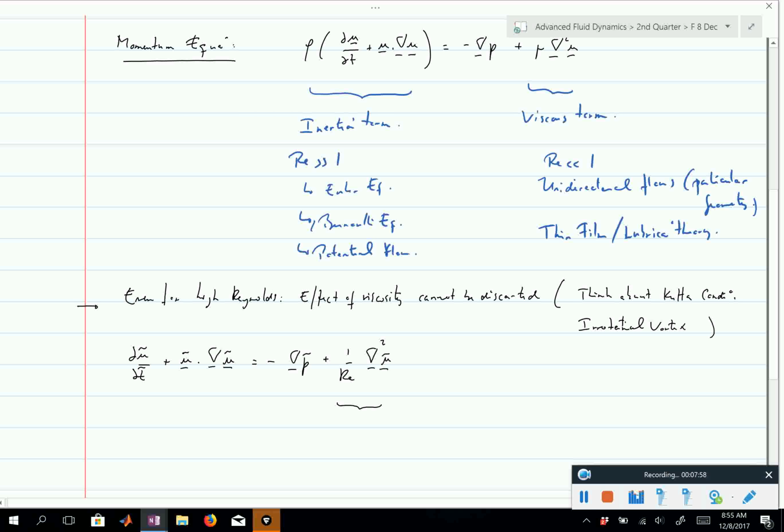Right, and I think for an irrotational vortex, this is the best introduction to a boundary layer, because what you do when you model a vortex with an irrotational vortex is you say, well, the flow everywhere is inviscid, so it's irrotational, but I'm stuffing all of the viscosity, all of the vorticity, and therefore all of the effect of viscosity, at just a single point in the center. A more physical model was the Rankine vortex, where you did have a finite core region with vorticity and therefore, if you want, the effect of viscosity.